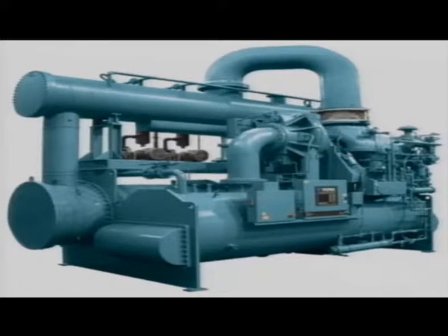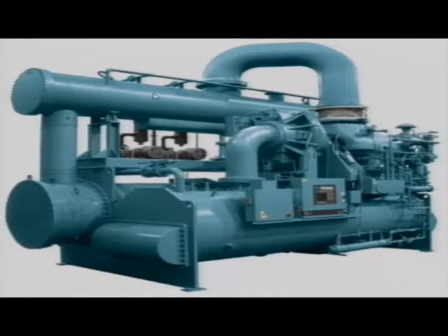Vapor compression system, the chiller of a central AC plant. So what this thing does is, right here in this part, there is a compressor which is operated by a motor. It's further behind this, we can't see that. It compresses the gas, sends it out into this big thing where you have water going through this, which condenses it, and this becomes a liquid refrigerant here. Then it comes down here, it is throttled, and here we have another set of pipes bringing warm water in, which gets cold and goes out as chilled water.